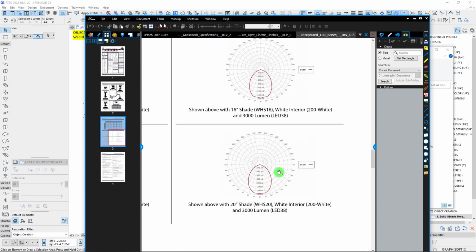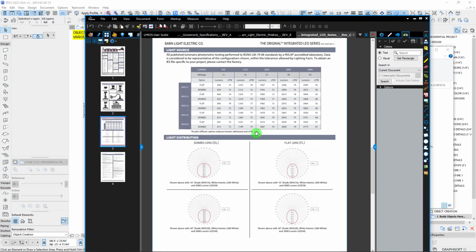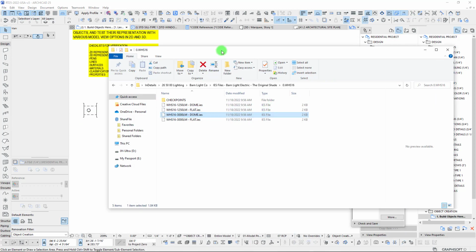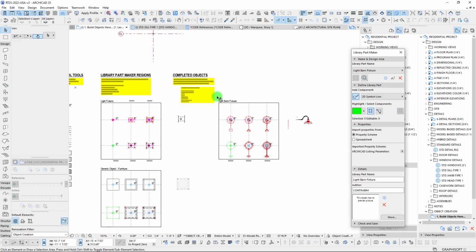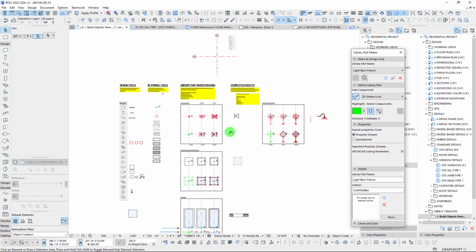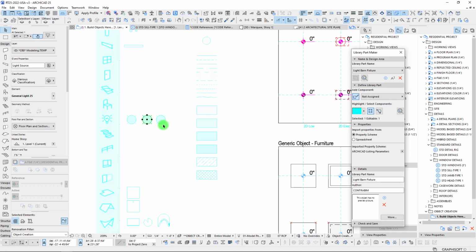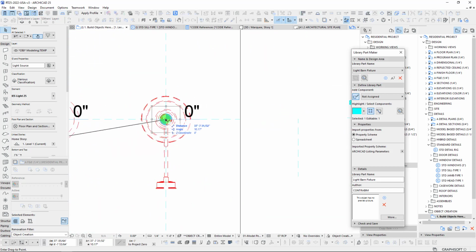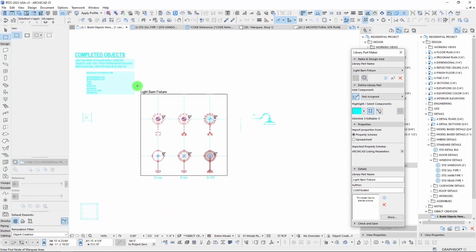Not sure really if that's going to be a huge difference, but nonetheless, we're going to go ahead and use those. We'll definitely use the 3000 lumens. So, how do we add these to our model element? Well, number one, we have a few placeholders over here. We're going to grab one of these that's an IES light, copy this over, and place it right here under our fixture.